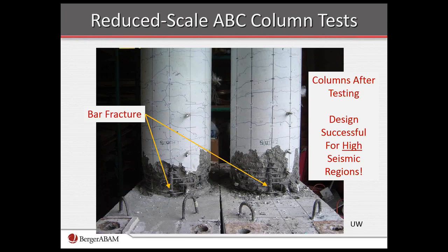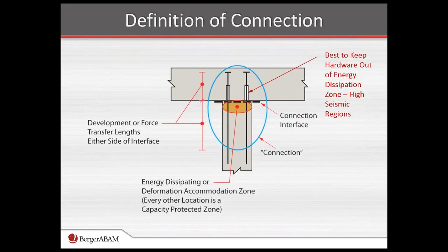So this is what we're looking for in high seismic regions, which stay obviously in design. The specification keeps you a little shy of the point where you're actually breaking the bars, but you do get quite a bit of ductility from these. So we've gone through effort to prove that the details in the laboratory actually will deliver what we need in the field.